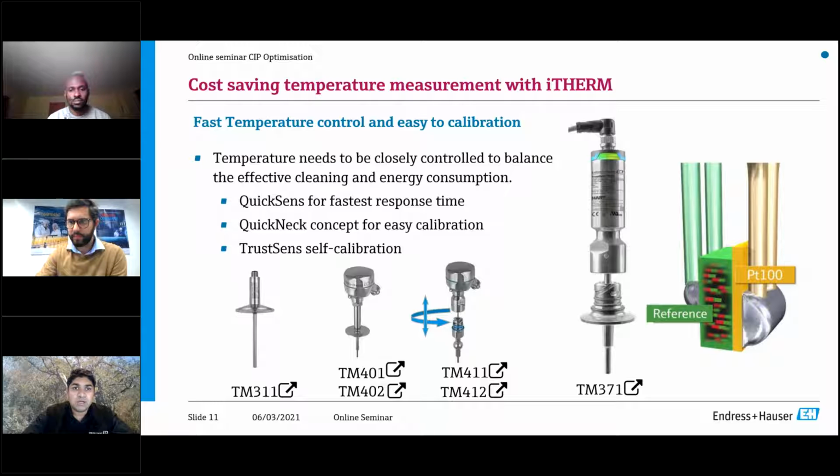And how we managed to achieve this was we mounted the physical sensor not in the stem, as you want to call it, but directly on the tip of the temperature probe, thus allowing us to be as quick in response as possible. And with regards to our response time, we are typically between 6 to 8 times quicker in response than your typical PT100 that you use.